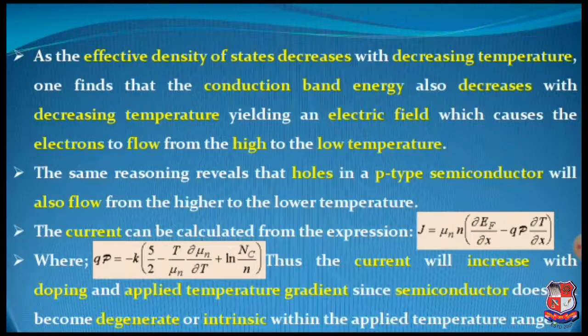So this way we can distinguish the two types of semiconductors, and this was measurement technique number 3. Already we have discussed 2 probe, 4 probe, and now in this particular lecture we have gone through the hot probe method.